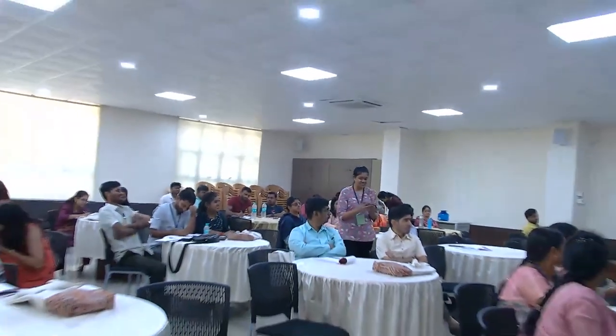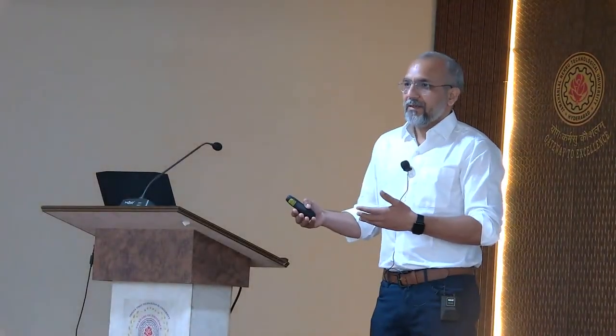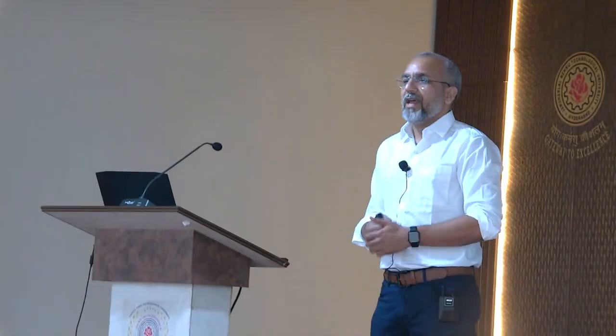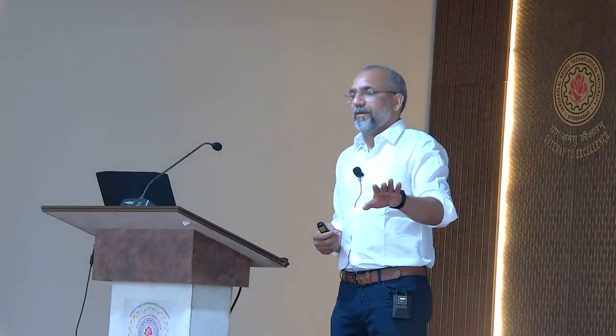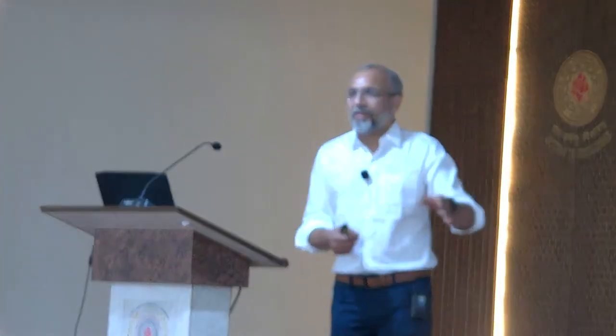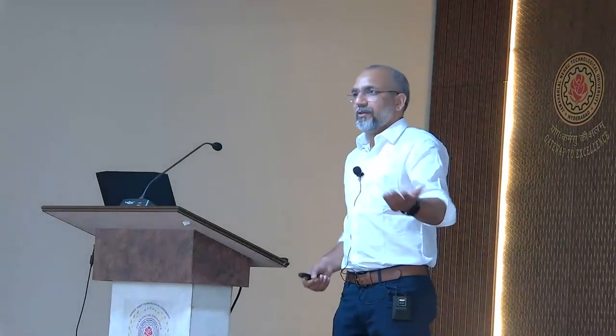What about the sample preparation for SEM? For SEM, there is no need for very specific sample preparation if it is conductive or a metal. But if it is non-conductive, then maybe you do some coating to make it a little bit conductive. Otherwise, for SEM, it's straightforward. It's very easy to prepare a sample. For example, you have a nanopowder, right? Simply take a tiny nanopowder, put it on a silicon substrate, and then you are ready to go.